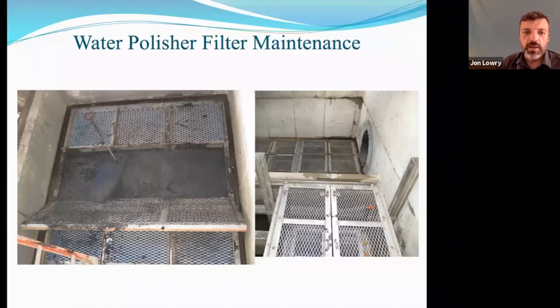And we've had a few instances where the contractor shows up, starts draining the baffle box, but didn't bring the filter replacement. So it causes a whole second cleaning to be required to come out and drain the box again and put the filters in. And in the design specs, we do make sure to include the manufacturer's specifications and the requirements for which filters are required and all that kind of stuff.